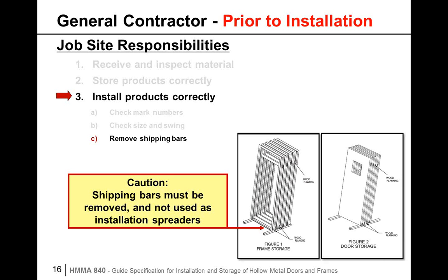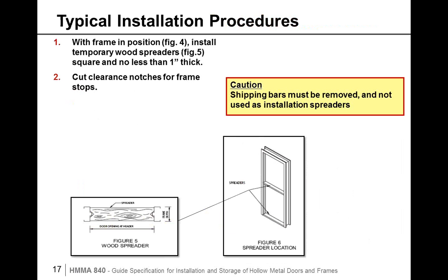The next thing prior to installing, the shipping bars must be removed from welded frames. Now, that's just a temporary spreader. A shipping bar, all manufacturer instructions and industry standards clearly recommend that those shipping bars must be removed. They are not an installation spreader.